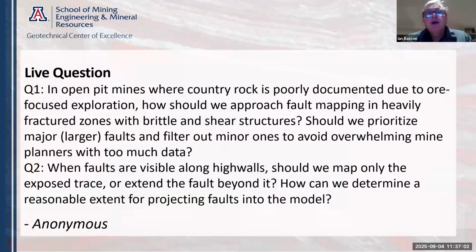So should we prioritize major, larger faults and filter out minor ones to avoid overwhelming mine planners? Well, it's not the mine planners that you have to worry about. It's really the geotechnical engineers. So the mine planners are sort of a bit downstream of that. There does come a point, when you say minor ones, where you're looking at these things and saying, well, I can only see them on one bench. So maybe they're going to cause a wedge failure or a local toppling failure or loss of bench definition.